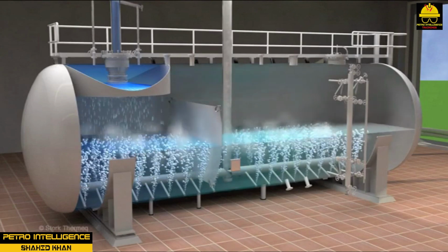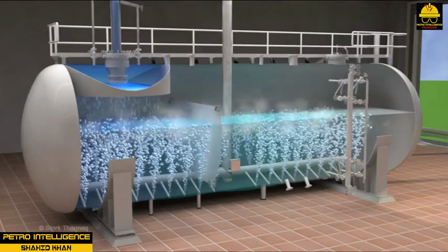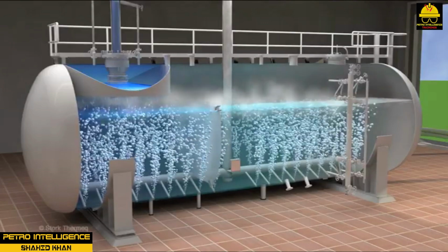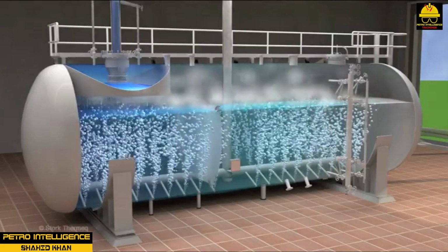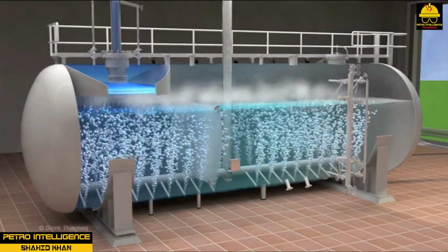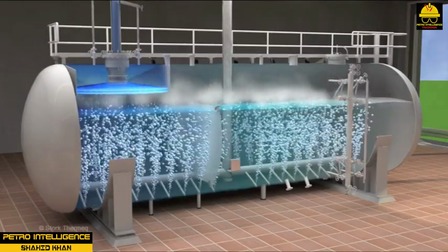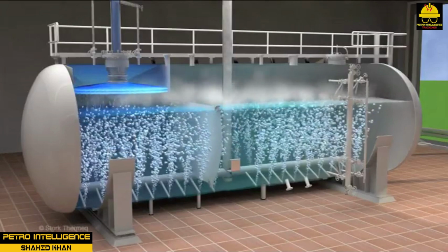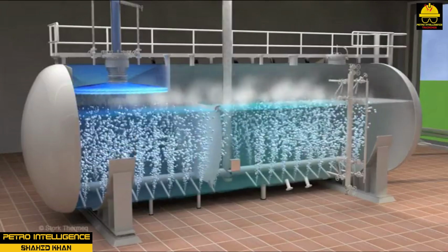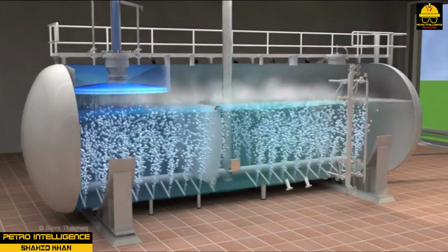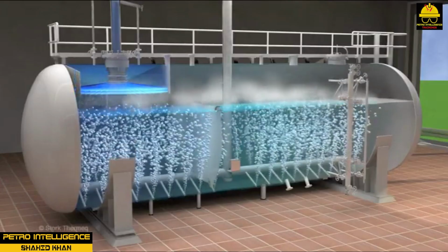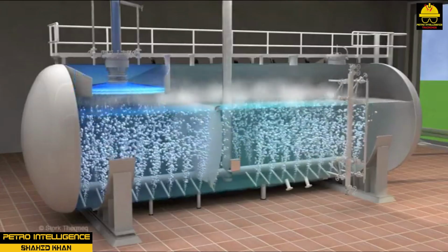Dissolved oxygen passes out the vent with the steam. Deaerators come in two basic designs: spray and tray. Spray deaerators inject steam directly into the water. In the tray design, steam enters at the bottom and water enters at the top. Water drops over a series of sieve trays that provides good contact between liquid and heated vapor.